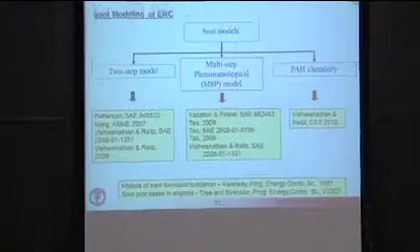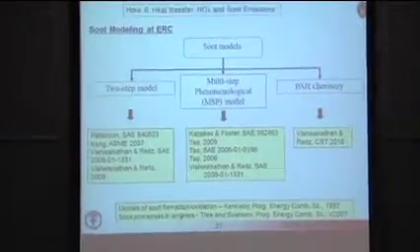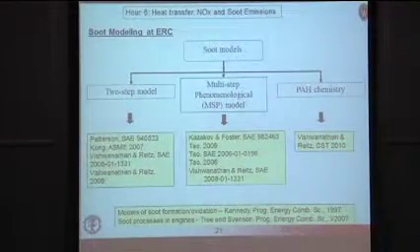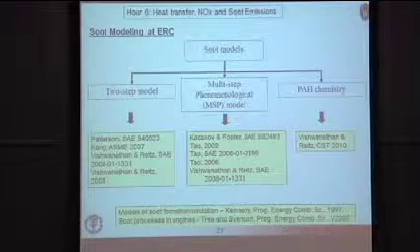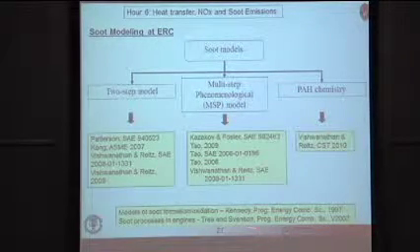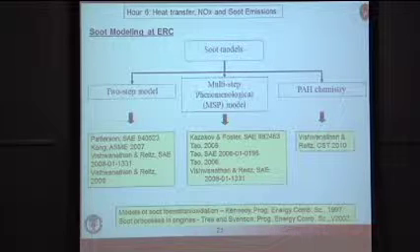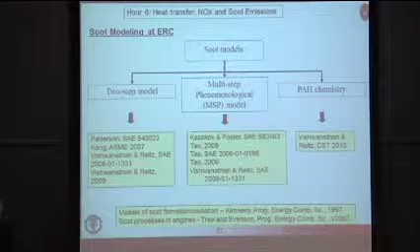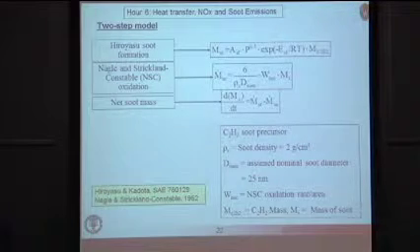Okay, so to finish up, let's talk about soot models. There's a long history of models that we've looked at in the Engine Research Center, starting with the simpler two-step models, so-called Hiroyasu models, looking at multi-step phenomenological models, and more recently, trying to include more PAH chemistry in our soot models. If you're interested in reading up about soot, there are some great references listed down here that describe soot processes in engines and in more general applications.